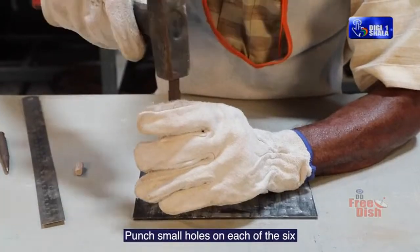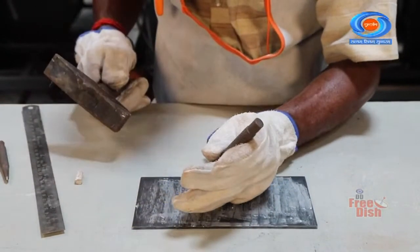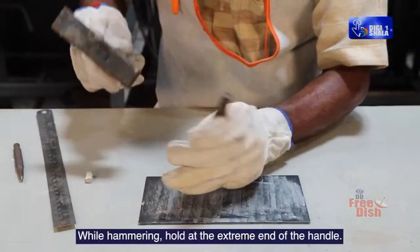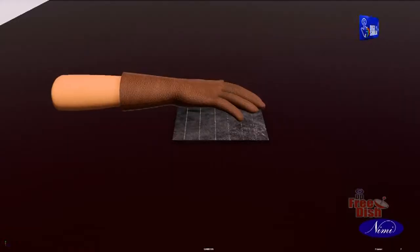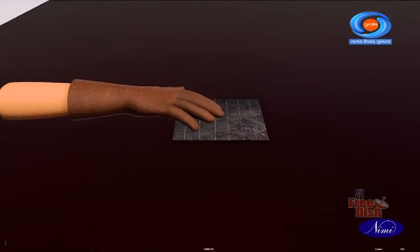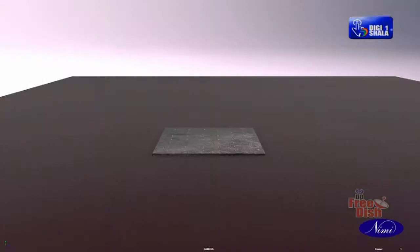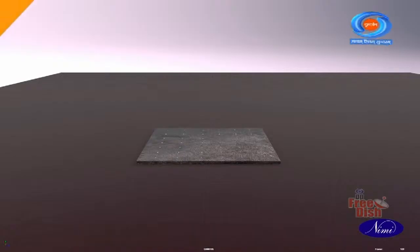Punch small holes on each of the 6 lines with the dot punch and hammer. While hammering, hold at the extreme end of the handle. Visually check the marked lines for parallelism and correctness. Pitch is the distance between the 2 consecutive dots.